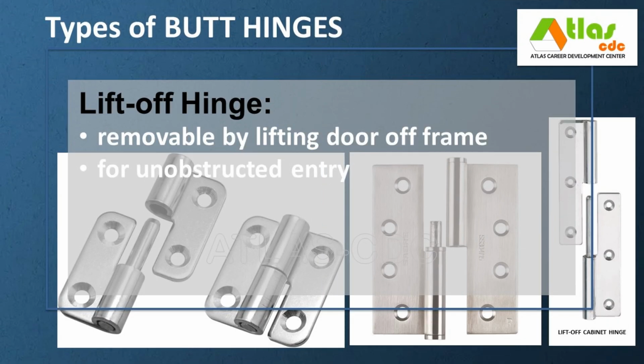Lift-off hinges, also referred to as removable hinges or door removal hinges, are engineered for rapid, tool-free door removal by simply lifting the door off the frame. Lift-off hinges enable swift access for maintenance, repairs, cleaning, or moving oversized equipment. Typical applications include machinery access panels, generator rooms, HVAC closets, and specialized cabinetry where unobstructed entry is periodically needed for large deliveries or equipment service.